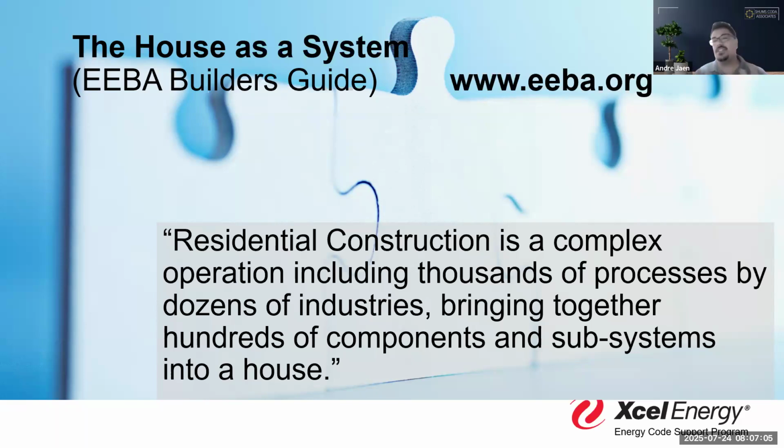So you're looking at all these different individual products, some of which are definitely designed to be tied together, right? Think like Tyvek and all of its tapes and sealants, right? Everything that's proprietary in that space, versus instances where you're doing it yourself. That could be taped sealants, that could be foam sealants, and then plywood or OSB. That can be part of your air barrier assembly, right? That can also be our stuccos, right? That can be our adhered masonry veneers. There's multiple ways to think about this, and each of them has a role to play in this assembly.